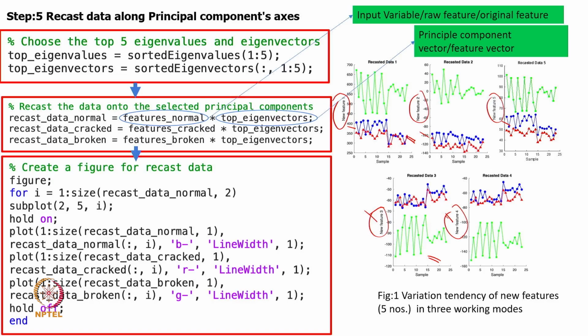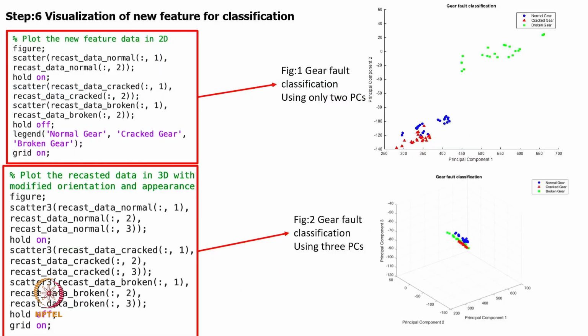Now, I can think about 2 ways. One is that maybe there is a subsurface crack and the vibration signal is not good enough to pick up that signal, and we need to change the sensor, or maybe get another kind of sensor to get a better response, or maybe we go ahead with the next stage of processing. So, PCA is one technique which we have used, but we should go for some other techniques so that we can filter out those things. These are also important and we can think about that.